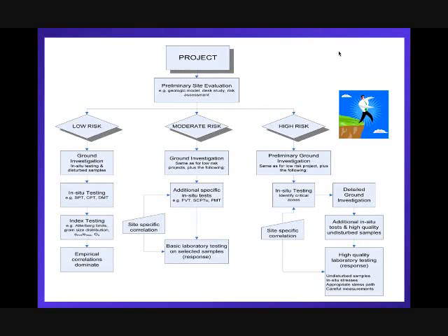But for moderate risk projects, often a basic site investigation, combined with maybe some additional in-situ testing. For example, if you had soft clays, you might do some field vane testing. If you had some very stiff soils, you might do some pre-bored pressuremeter testing, some Menard type pressuremeter testing.